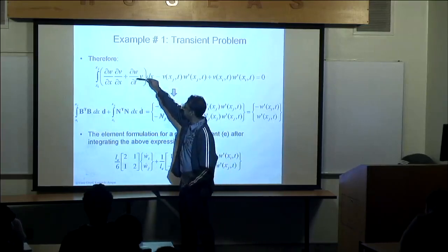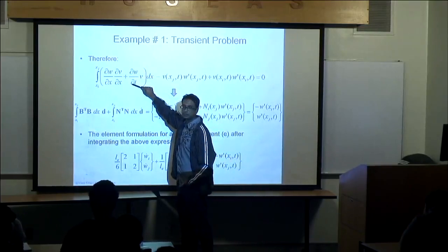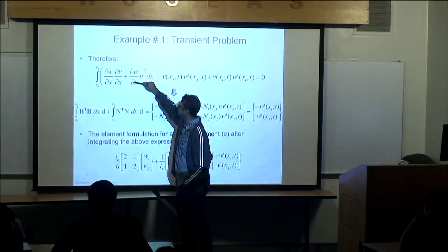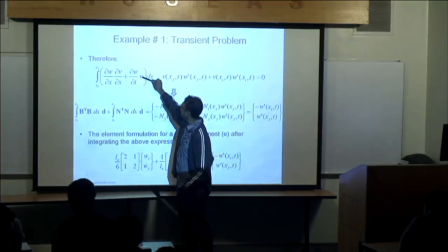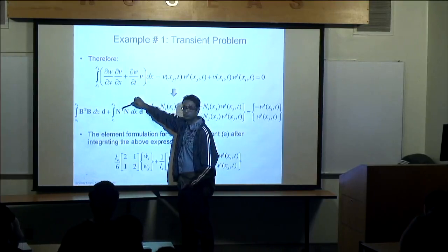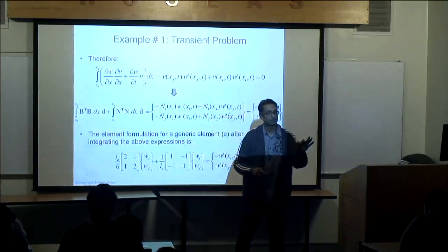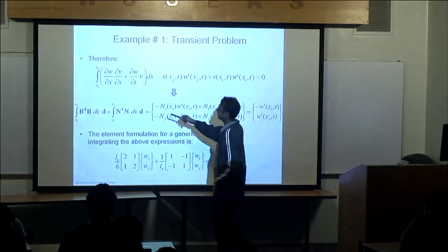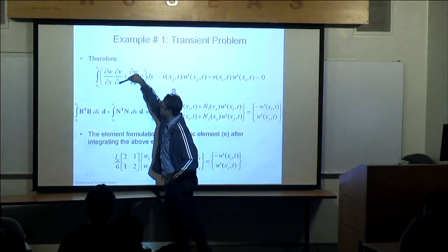I also notice here that this quantity, I just evaluated that just a minute ago. I call this the derivative of W with respect to t. We found it to be N bold D dot, in essence. While V was selected as N transpose bold. Remember, V we're selecting to be N transpose bold. Okay? And we also found the derivative of N transpose bold is basically B transpose bold. So that's what that turned into.